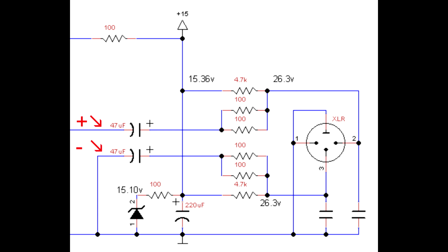Now some amplifiers will actually have real plus and minus signals. This particular circuit kind of has a fake negative circuit. Actually, it's tied to ground. So ground is the negative side of the equation. Now, if there is common mode, both in the ground and in the plus signal, then it is a differential pair, even though one side is tied to ground. And they chose to have exactly the same matched impedance going to the preamplifier offboard.